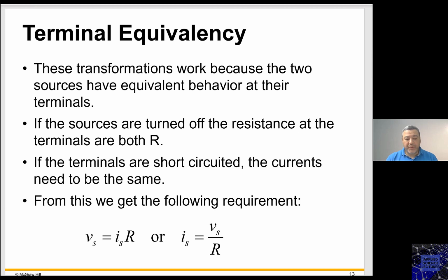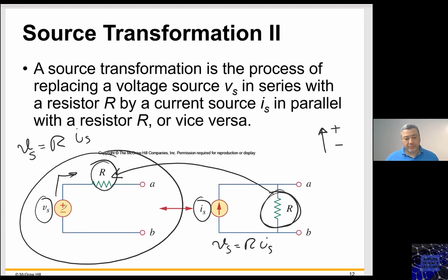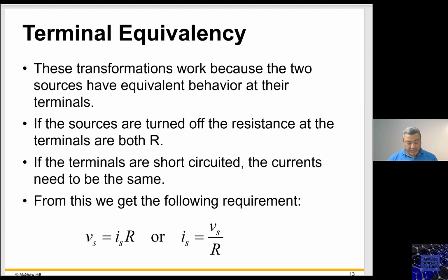Now you have to keep in mind, you cannot do any transformation if this resistor is 0. You cannot do any transformation if this resistor is infinity or does not exist. In other words, if you have a voltage source in a circuit, right?